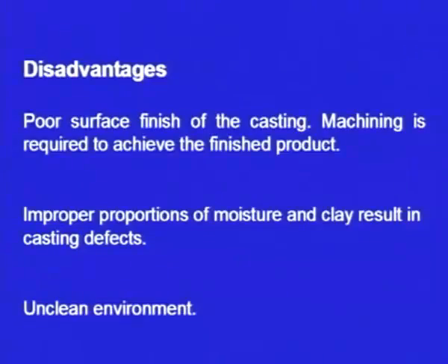It will be irregular, it will be rough. So to get a fine surface finish, we have to do machining operation. For that we have to spend more time, more labor, more money. So this increases the cost, this increases the time. So this is one of the major drawbacks of the green sand molding.